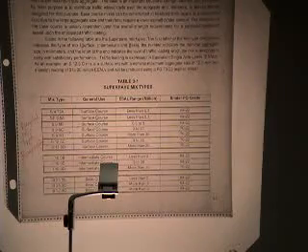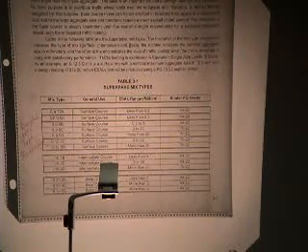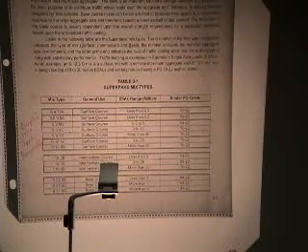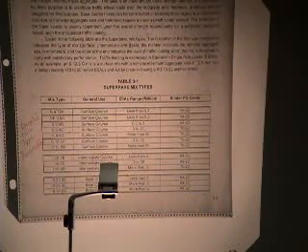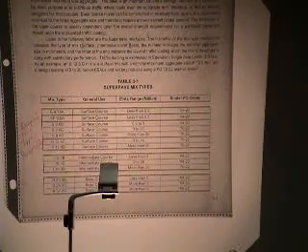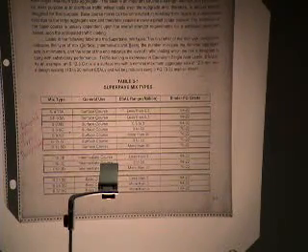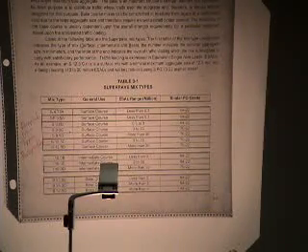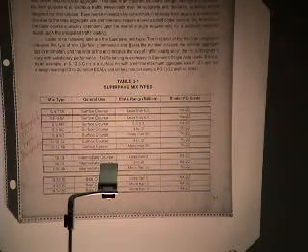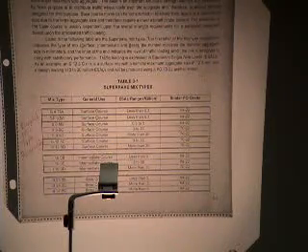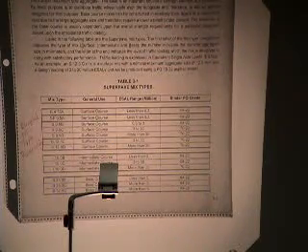The C level probably is for heavy primaries and some of the rural interstate system. And then the D level is for very high traffic interstate type traffic. There may be some primary routes that fall in that same category, but for the most part it's for interstate type traffic, where not only do you have a lot of vehicles, but you have a real high percentage of trucks. And that's what drives that.